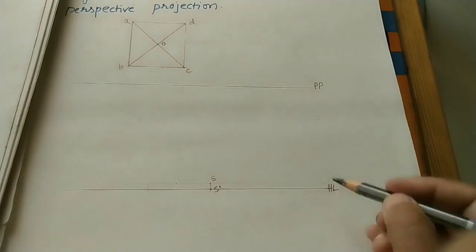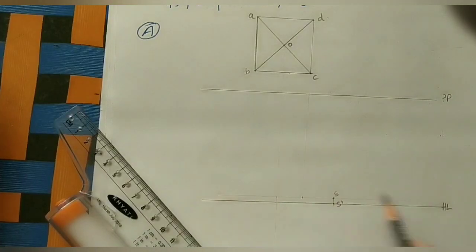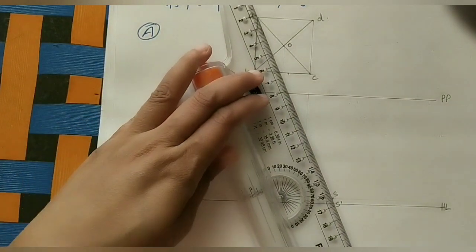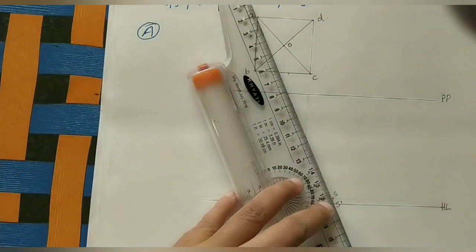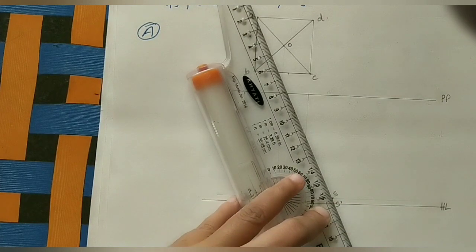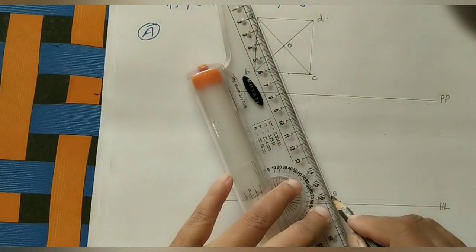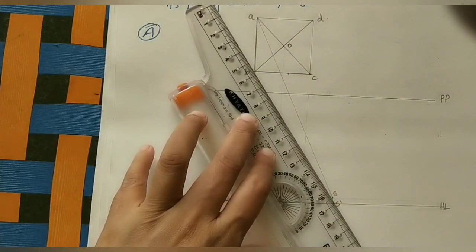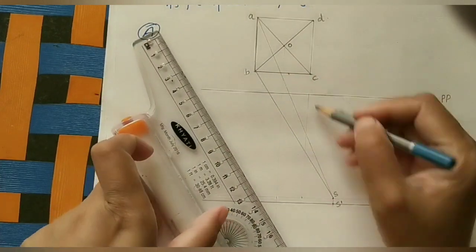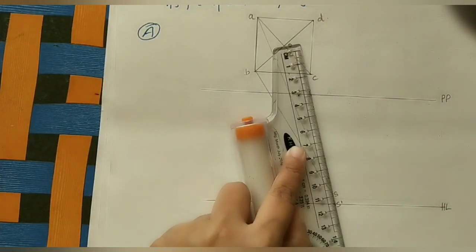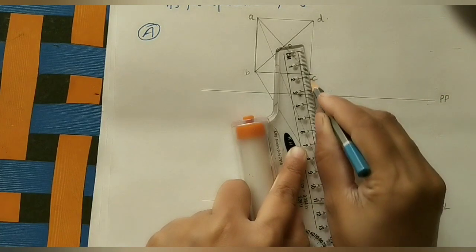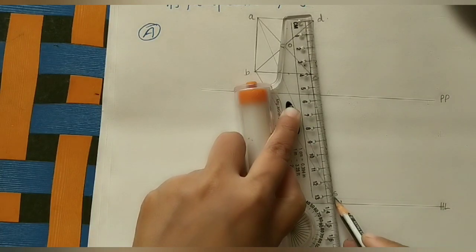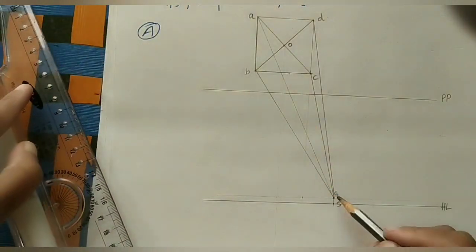So we got PP line, HL line, GL line. So after getting all the lines, here in the top view, we have to join all these points to the station point with the help of scale. So do with thin lines in the sheet. Here for getting the clear view, I am just doing the dark lines. We do all the diagram with the pencil only. Join to S, A point, similarly B also. Next from C to S. Next D to S. Like that, we have joined all the points to the S point.